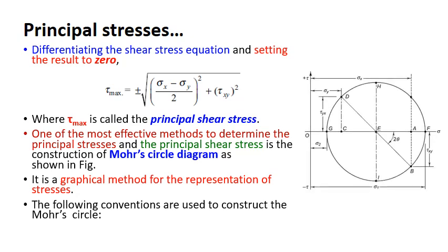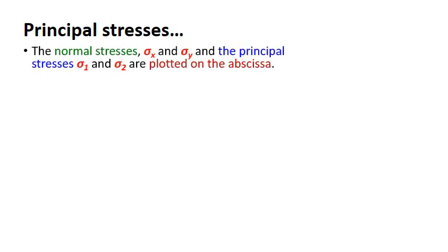So this is the Mohr circle you would have drawn in the mechanics of solids. Let us relook into it again, how to construct it also. First you will be given a state of stress acting on an element. When we say state of stress, it means we are giving the magnitudes of different components of stresses acting on the element: sigma x, sigma y, right?